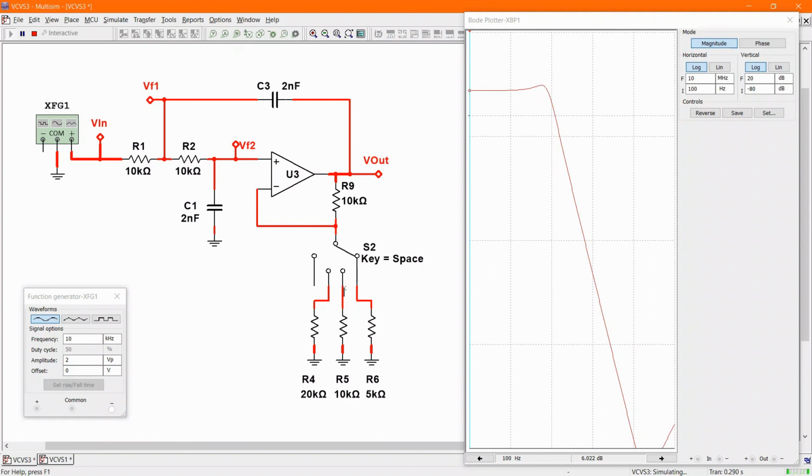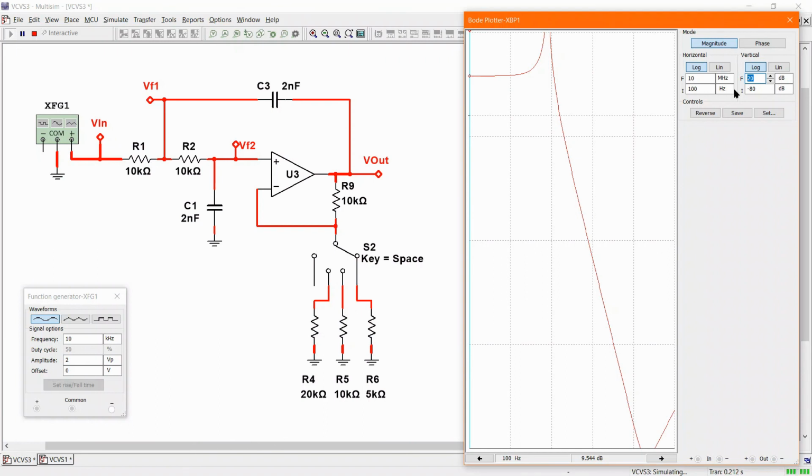Now let's go to 3 times. So this is a gain of 3 times. And we restart the simulation, and now you can see the nominal gain is about 3 times bigger, but at the resonant frequency that's created, we can see a big spike. In fact, if I make this like 60 dB, you can see that the output rises like 60 dB, which is a significant increase.